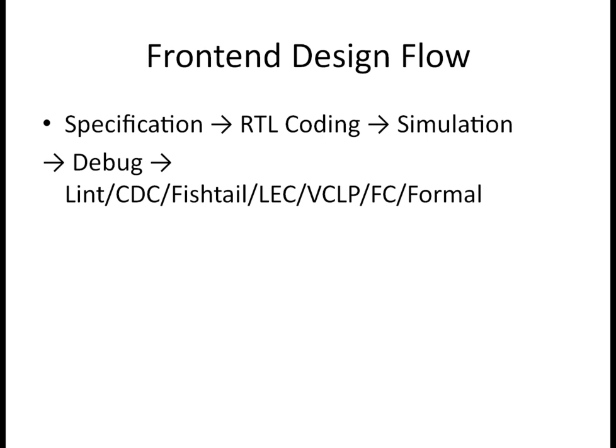So then UPF will be written. UPF is unified power format, where we'll be writing the power intent, okay, and that UPF has to be fed to this VCLP tool and we need to make sure the UPF is correct. Okay. So if the UPF is not correct as per the RTL, this tool will throw violations. Sometimes, for example, your isolation is not correct, or level shifter is missing, or power state table is not correct, or power state is duplicate. So those things will be coming. We need to debug those things and correct them as per this flow.